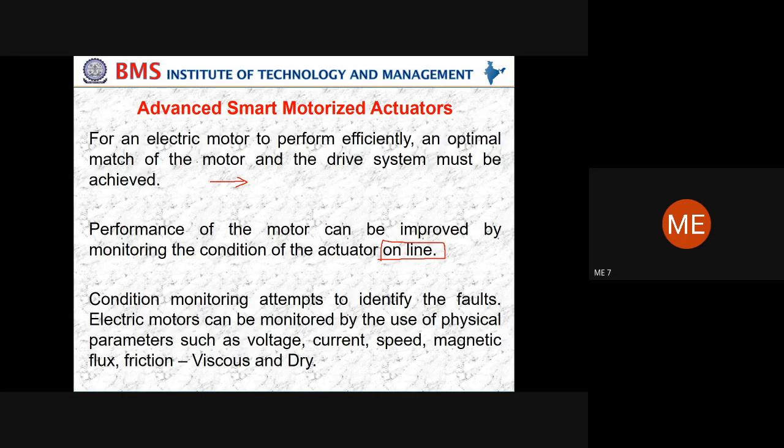If you observe some companies, they have some time for maintenance. During that maintenance, they are not going to operate the machines. They will close off all the work, and then do thorough maintenance without running the machine. Nowadays we are not going to do any offline monitoring. Remember very clearly, very important: nobody wishes to stop the machine for a minute. So, ruled out is offline monitoring. Always it should be online monitoring.